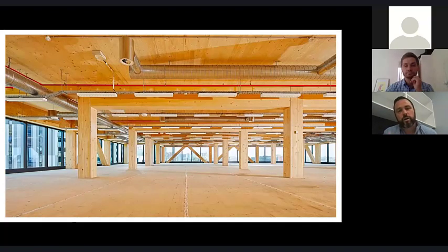So it's bringing a concrete construction methodology into the mix, but using timber and with all the benefits. And if you can achieve this, there's a lot of restrictions though with engineering and architecture that Nathan will talk about, but it will really allow you to focus on building that structure up on critical path, as well as the facade, without dealing with that materials handling during the critical path elements.